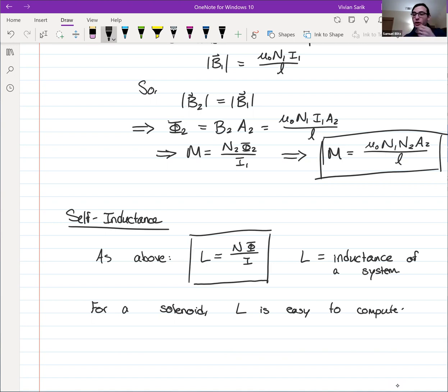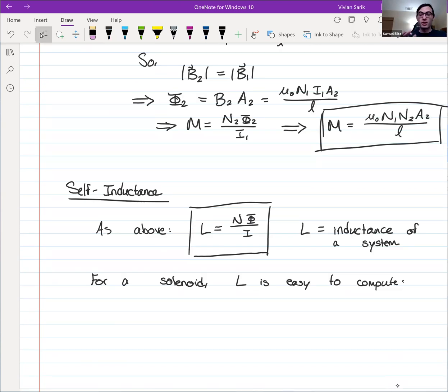For a physical solenoid, can we compute L for a changing value of I? Yeah. In fact, if I changes, so will the flux, and it turns out that the way they change precisely cancels out, so you're just left with a constant. So the inductance for a solenoid is N times phi over I, which is just N times BA over I.